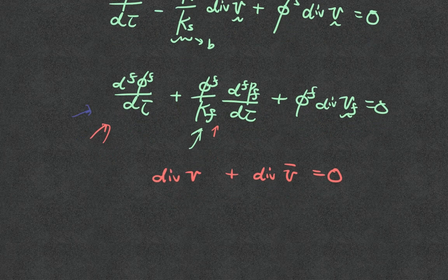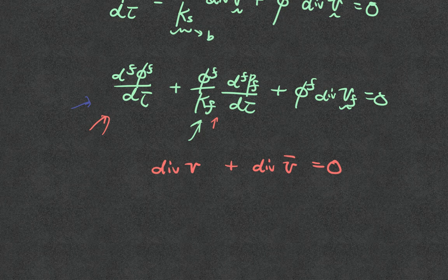Previously in the undrained case, I simply have divergence of V, right? Now even in the undrained case, I actually have something that is compressible, isn't it? Because divergence of V equal to 0 implies incompressibility. If I change these directions, it's compensated by the other two directions so that the sum becomes 0. So I did not change the size at all. But here, even in the undrained case, I can actually compress the material a little bit because this term is not equal to 0.